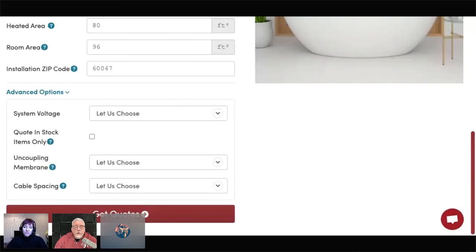And the reason why is because carpet, laminate, LVT are products that have a maximum temperature requirement. You cannot go over a certain temperature. So carpet could be 82, it could be 84, it could be 79, whatever that manufacturer says, and you cannot let the floor get hotter than that to keep your warranty.